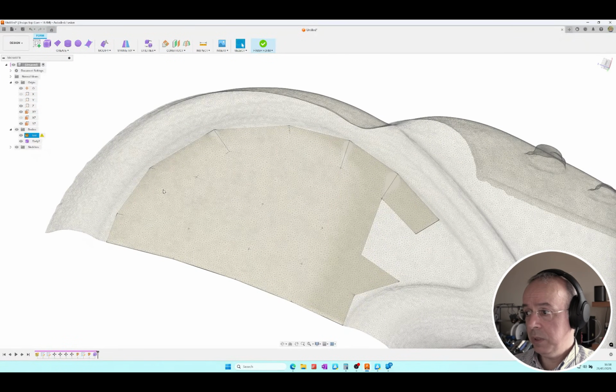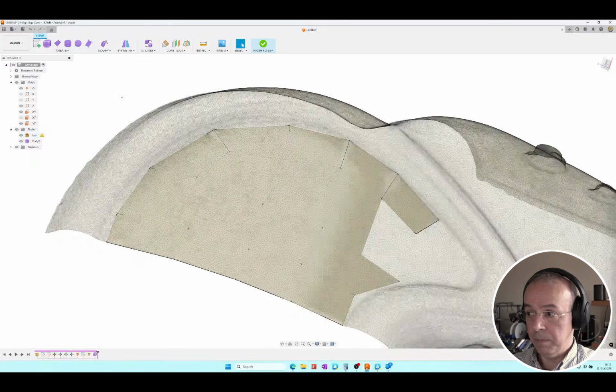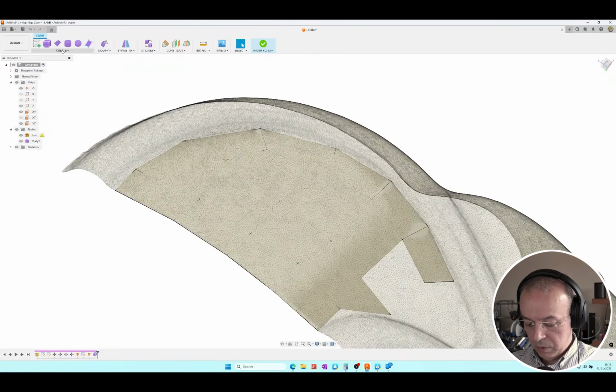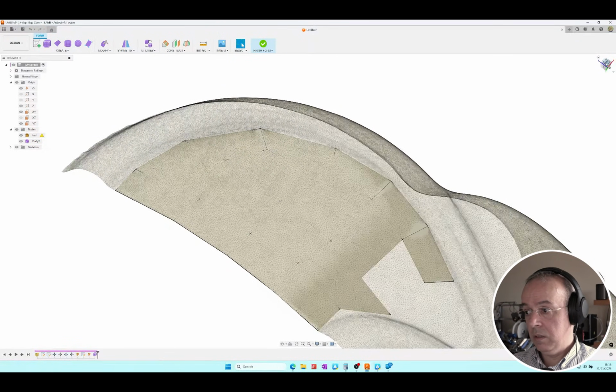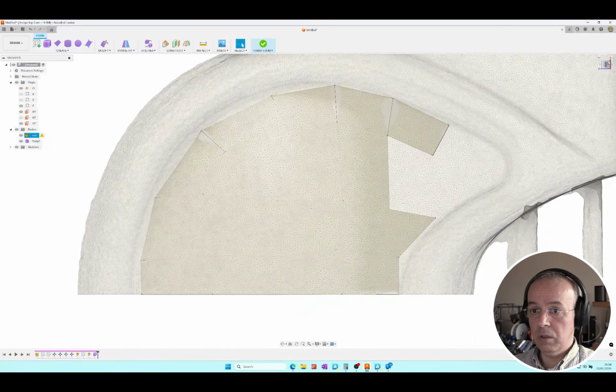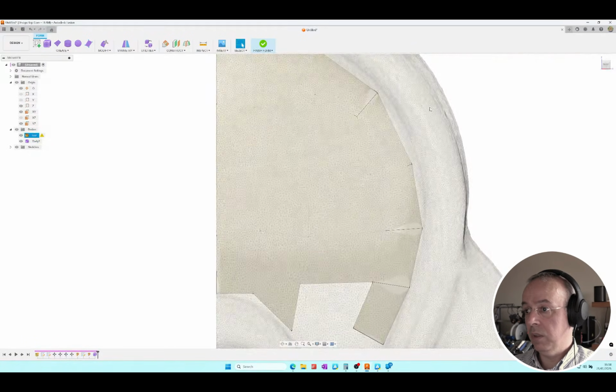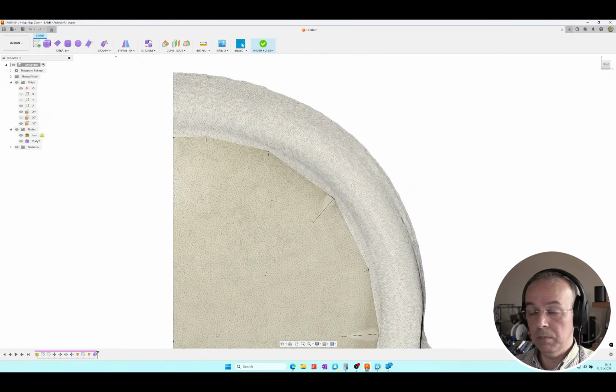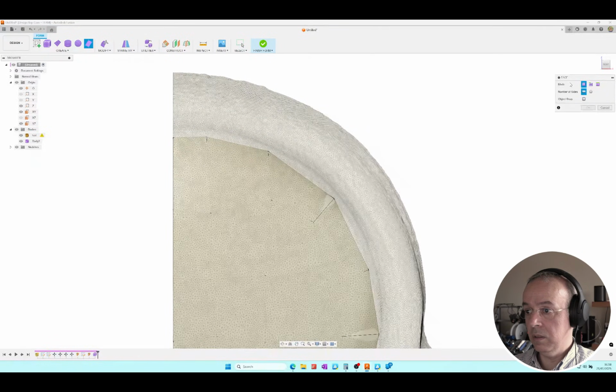Let's use Alt+1 again to view the polygons in box mode and try to trace some of this edge running along the top, at least up to the front, so you can understand the importance of the face command. I'll activate the top view and rotate this to better see what we're trying to do. Then activate Object Snap again. I'd say I'm roughly aligned with the top.